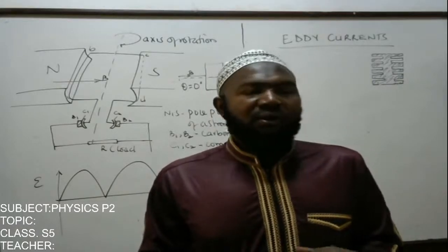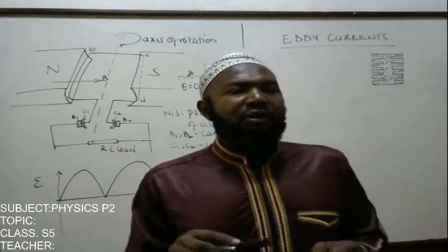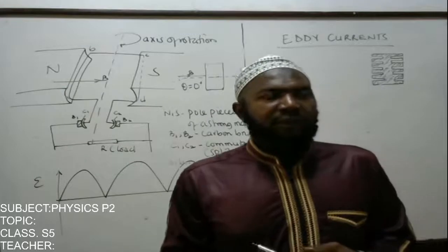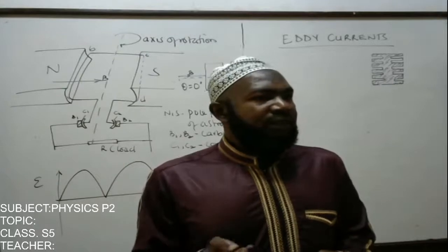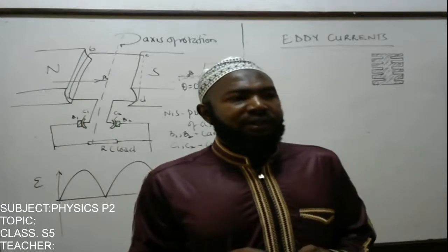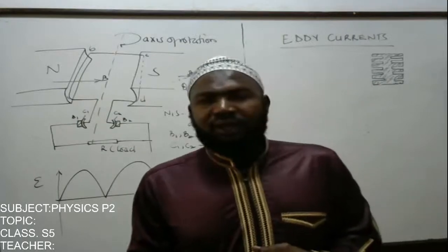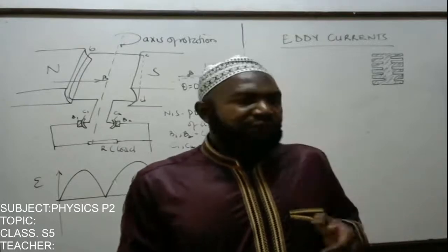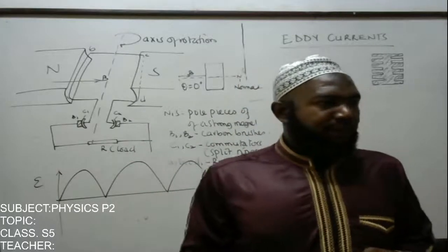We are saying the crucible is a metal container containing the metal to be melted, surrounded by copper coils fed with high frequency alternating current. The liquid flowing through the tube constantly keeps cooling it. So the rapidly changing magnetic flux linking the metal parts in the crucible induces eddy currents in the metal, which cause them to heat up and therefore melt. After melting, we can subsequently get different shapes for the different desired metal.